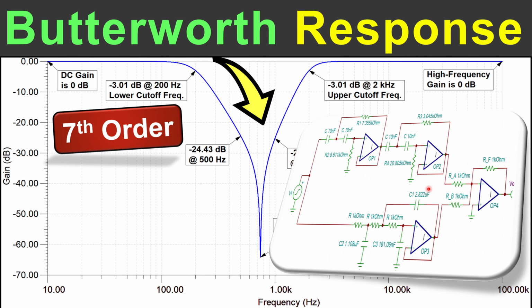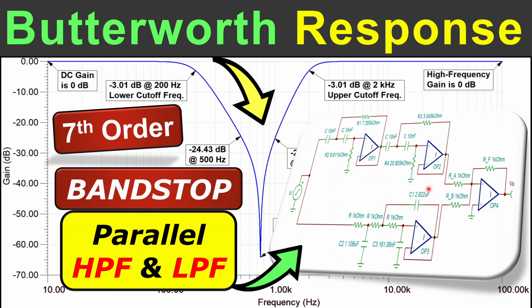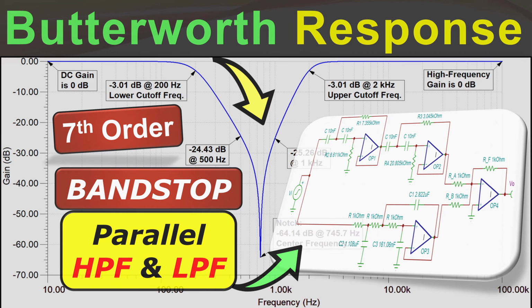In this example, we will discuss the bandstop filter design, where we use the parallel combination of a high-pass filter and a low-pass filter. It will be a wide band filter circuit, and we will use the Butterworth response for our realization. Of course, we'll see everything step by step and verify these in SPICE simulations.